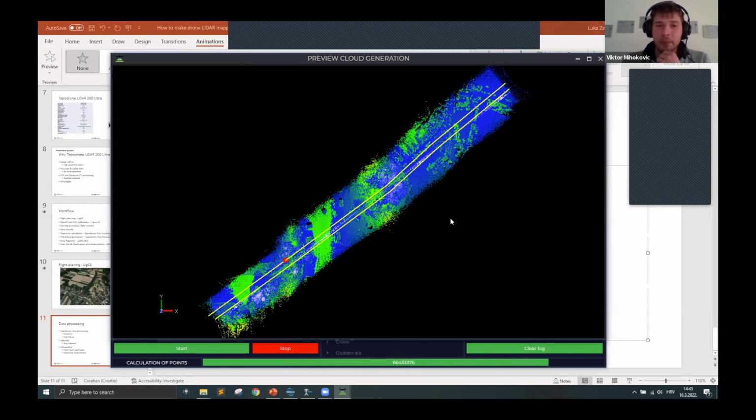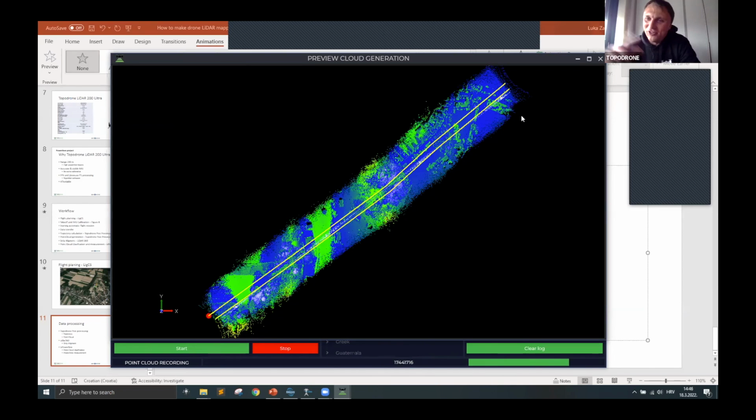Yeah, definitely. But from our experience, we would cut this part, the beginning and the end, out, where the IMU had the sudden movement, because as you can see, these lines are really next to each other, and UGCS is aware that the drone cannot make the adaptive turn, and it will not allow you, for just the power line survey, to use the adaptive bank turn every time. So from our experience, for lines really close to each other for power lines, it's better to use that and then cut off the wrong parts.